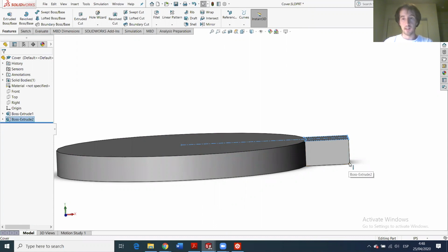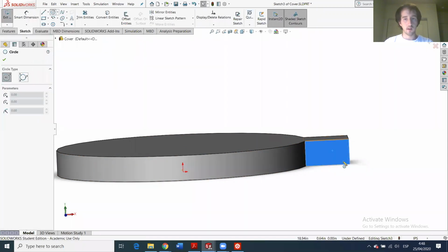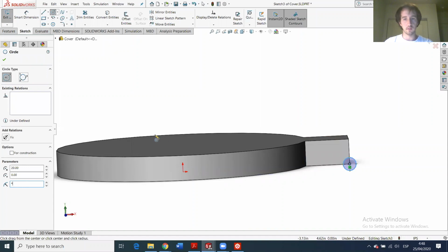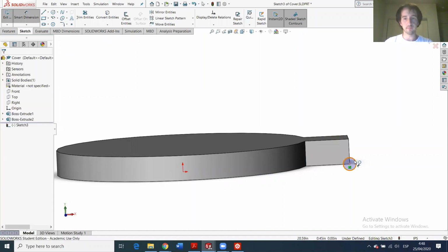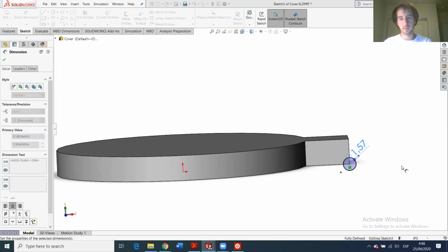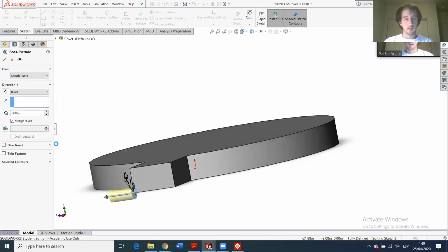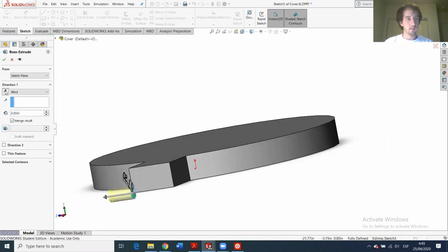And we know that here we will need the last point of the mechanism. So we're going to design it. So we're going to open a sketch here. And we're going to make a circle here of 1.5. Okay. And let's extrude it the other way to the next surface, which will be this one.